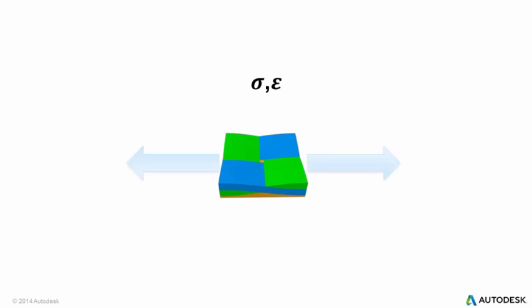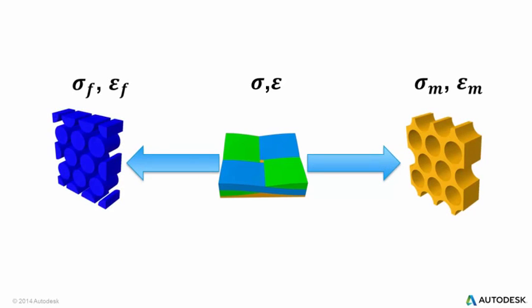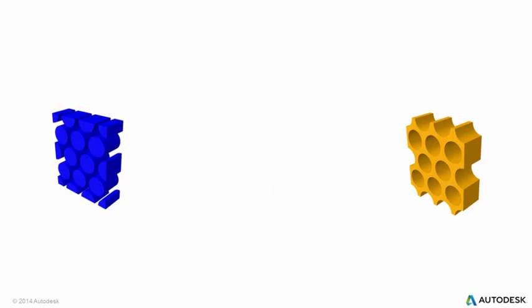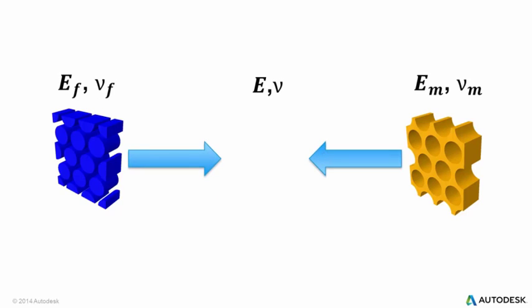Finally, for woven materials, the fiber and matrix information is easily acquired during a finite element simulation for both the fill and warp tows using the capabilities embedded within Autodesk Helius PFA. The response of the woven material is reformulated by identifying and propagating damage at the fiber and matrix level, which in turn is used to define the response of the composite material.